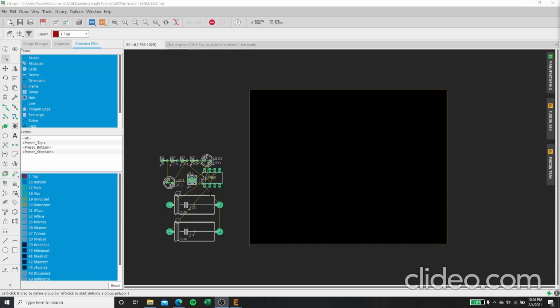One important thing to note is that there is no right or wrong way to lay out a circuit board. It is pretty much an art, and so whatever makes sense to you is good. Obviously, there are some ways that are better than others, some ways that are going to be cheaper than others, but it's important to know that there's not necessarily a right way to do this. A lot of times people will start with their biggest components and work around those, or if their board has any connections that need to be made on the outside edge, they'll put those components there first. It's really just up to you.